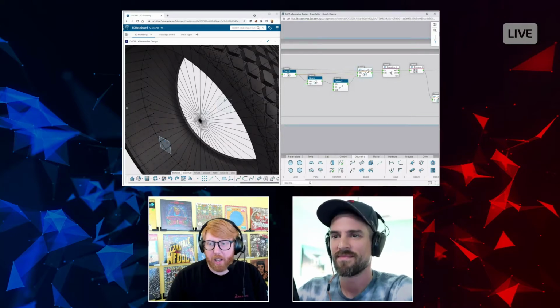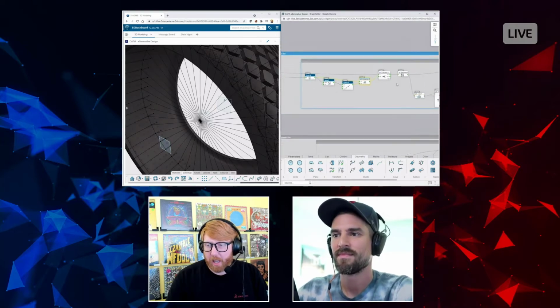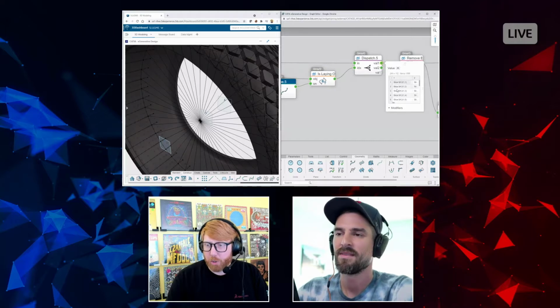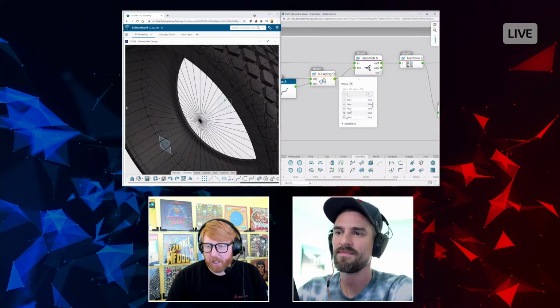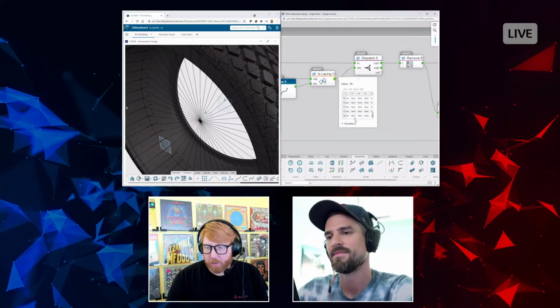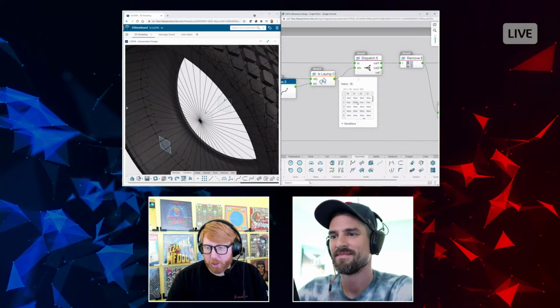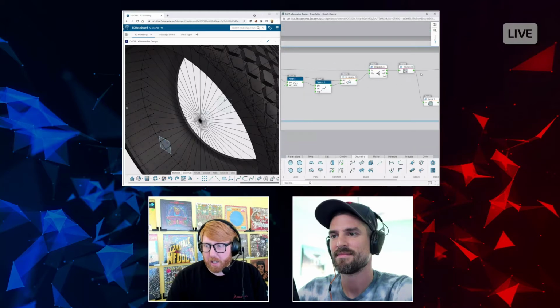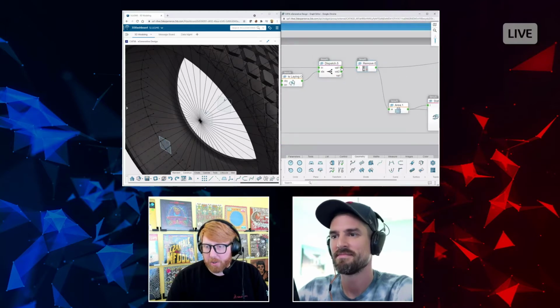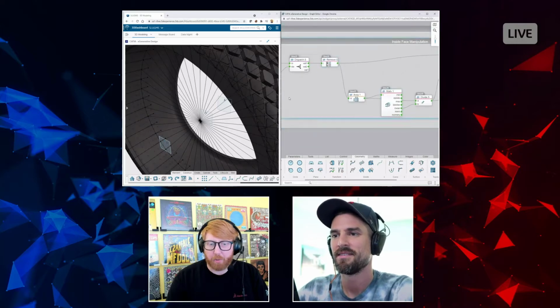If they are lying on that spline, then I run it through this thing called a dispatch. Basically it's a bunch of true false values. We'll find a true somewhere here, probably at the top. There we go. So all of these are true, and all of those trues are going to be removed from this list. So now I remove the empty values and I go from having 836 nodes to 792 nodes. Now I've removed all the faces I don't want, because I don't want those little tiny sliver faces.